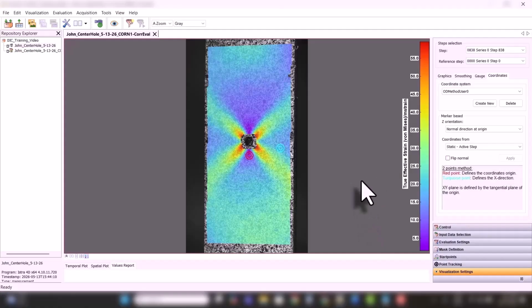the DIC system is going to look at a little group of points, a cluster of points that the origin is sitting on top of to estimate the local surface geometry and calculate a best fit surface or plane, and then determine a normal to that surface or plane. And that's the Z-axis, where the positive Z-axis is based on going outward away from the surface.